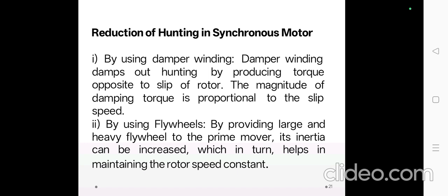The synchronous motor acting as a synchronous condenser is now connected across the same supply. This draws the leading current of I2 phase. The total current drawn from the supply is now the phasor sum of I1 phase and I2 phase. This total current IT now lags V phase by a smaller angle phi, due to which the effective power factor gets improved. This is how the synchronous motor as a synchronous condenser is used to improve the power factor of the combined load. As the power factor becomes very low, the current drawn from the supply increases to supply the same power to the load.